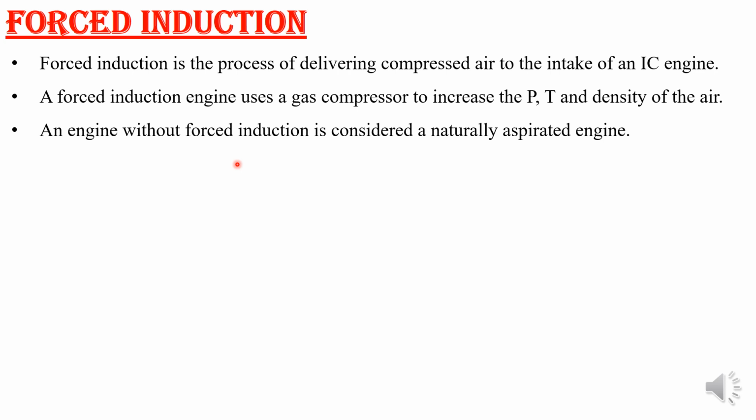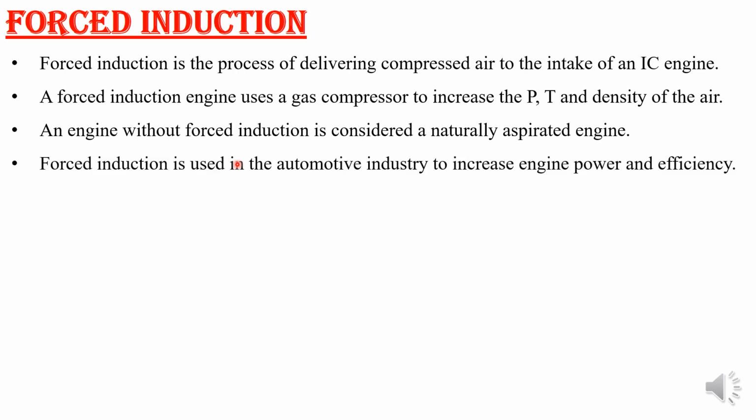Forced induction is used in the automotive and aviation industries. Many automotive and aviation industries use it because they have to get more power, and efficiency can also be increased by the forced induction method. We are forcibly increasing the density of air, so that the quantity of air going inside the engine cylinder increases.